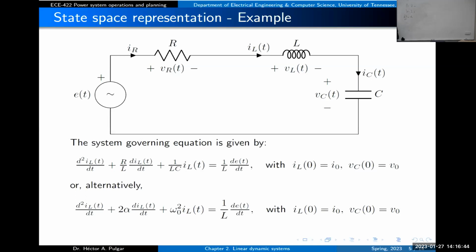In that case, what you will have here, you remember? Well, you look at the equation, then you don't have any damping. So you are going to have a system that oscillates forever, right? Of course, we do not have that in practice because you cannot have a conductor that has zero resistance. So if you build something in the lab, it will always die at some point.